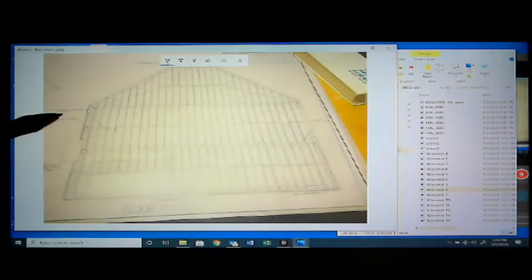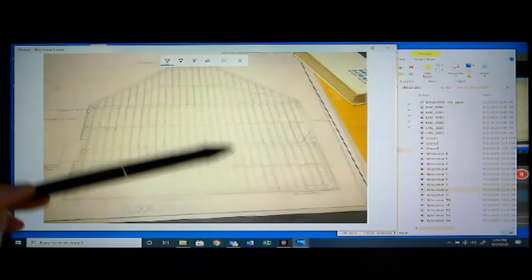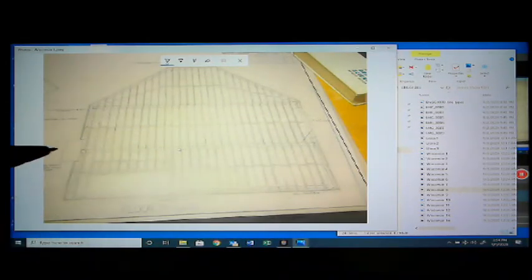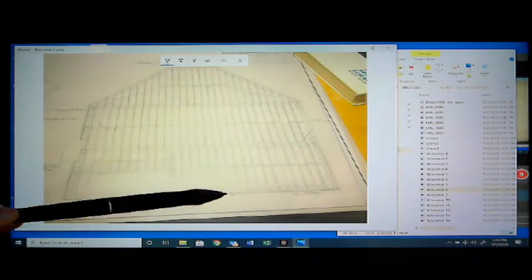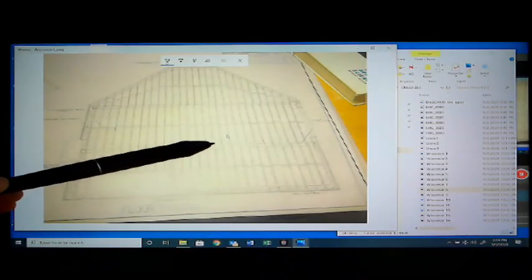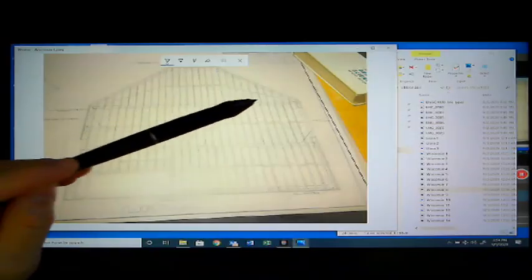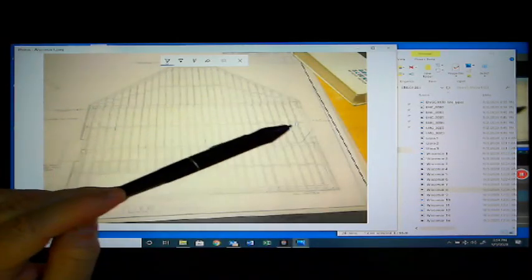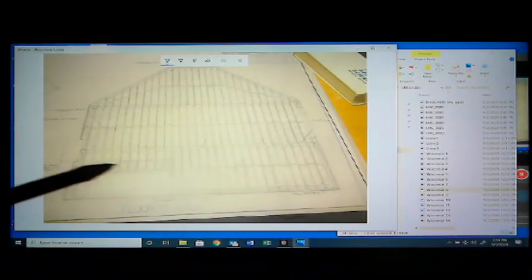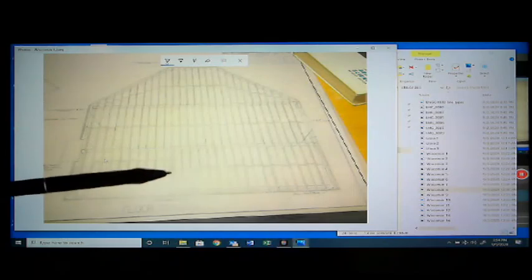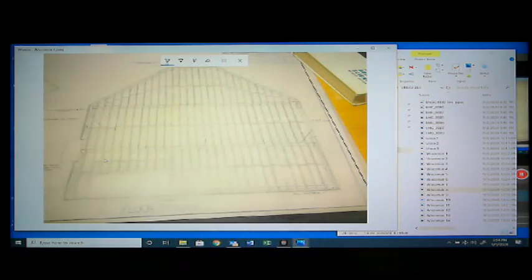And when I did this, I had to do all of the research and get it all checked by an architect to make sure I had all my numbers right. And so you can see how here's the joist coming across. Then we go over to another one, and they overlap there over the beam. We have the center stabilizers that are all in here. Okay, here we're having a bulkhead to make place for the fireplace. All things you've got to know how to build a house. So that shows how to lay all that out.